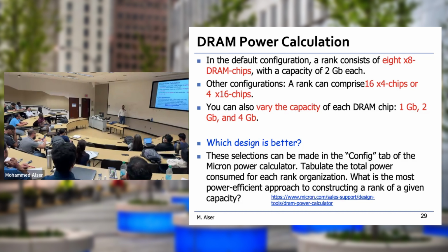He's saying that the DIMM operates on its own clock cycle, and the other DIMMs also work on their own clock cycle, meaning they are independent. They can work really at the same time, and each of them provides 64 bits. That's 128 bits per clock cycle, which is better than a single DIMM with larger capacity that only gives me 64 bits again, because of the same interface. That's a very strong, very valid question.